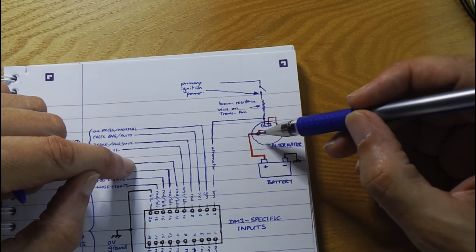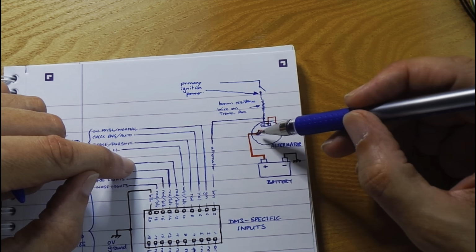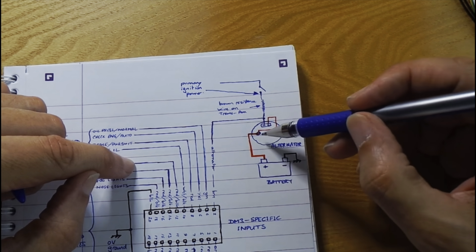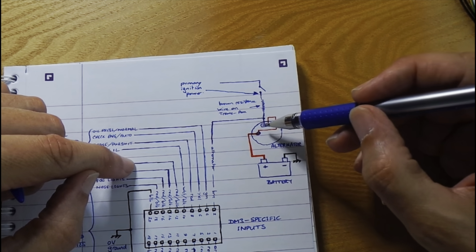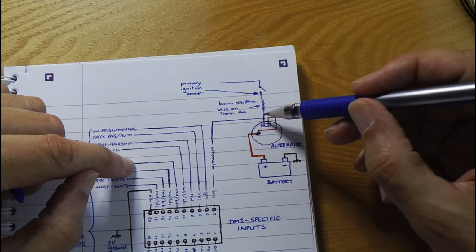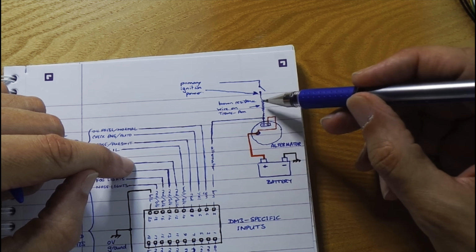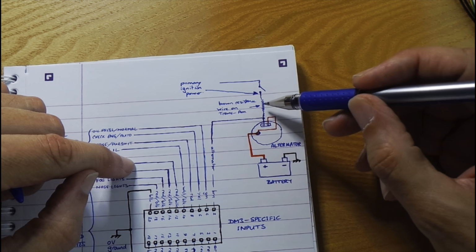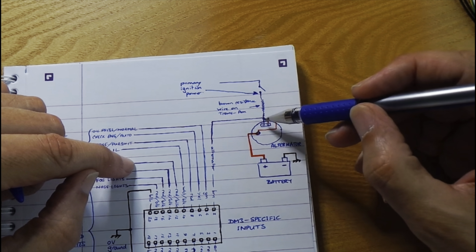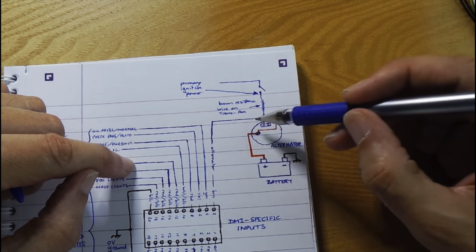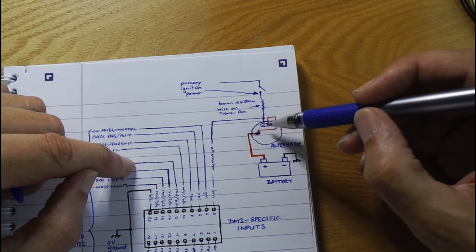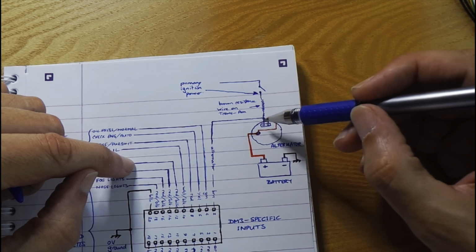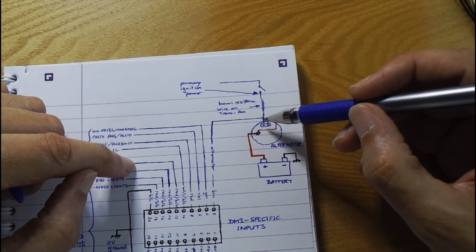You'll find that on the alternator you'll have a big output which is the main power output, which connects to the battery, and that output will also be connected to one of the smaller terminals. Now the other terminal, which will usually go through a warning light, a charging warning light, or on the Trans Am it goes through a brown resistance wire, you'll connect this wire here to that point, and the voltage difference between the battery voltage and the voltage being generated there is an indication of whether the alternator is charging or not.